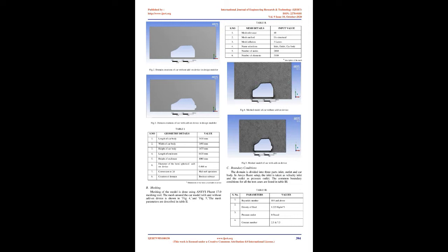vehicle stability, and a moderate effect on drag, i.e. fuel consumption. Rubal Chandra Dasa and Mahmood Riyada [6] have concluded that at a particular spoiler height, the spoiler that possesses a smaller angle of wind collision gives higher drag force. This is due to the fact that with a smaller angle of wind collision, the spoiler would create a smaller recirculation zone behind the rear end of the running vehicle. This implies higher pressure behind the spoiler but lower pressure behind the rear end of the vehicle. Rear spoilers redirect the airflow behind the vehicle and increase the negative lift of the vehicle.